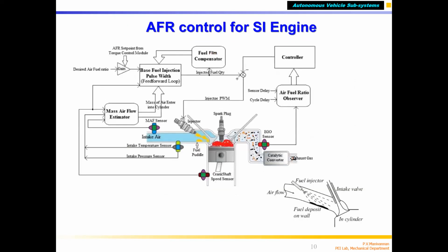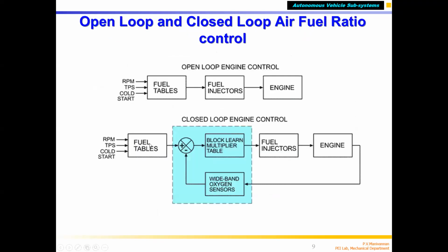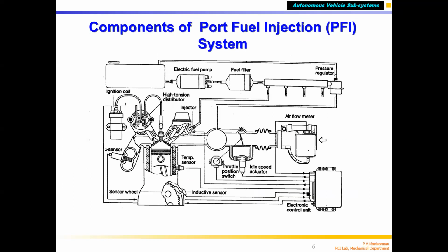What it means is we can see that inlet air is coming from here. The throttle body in the preview, I will show you the map where it is. You can see that this is a throttle. So the throttle is vertical. Now it is in the idle condition. Even though air is entering from the atmosphere, this air can go inside only through the bypass valve. So this is completely closed when throttle is 0%.